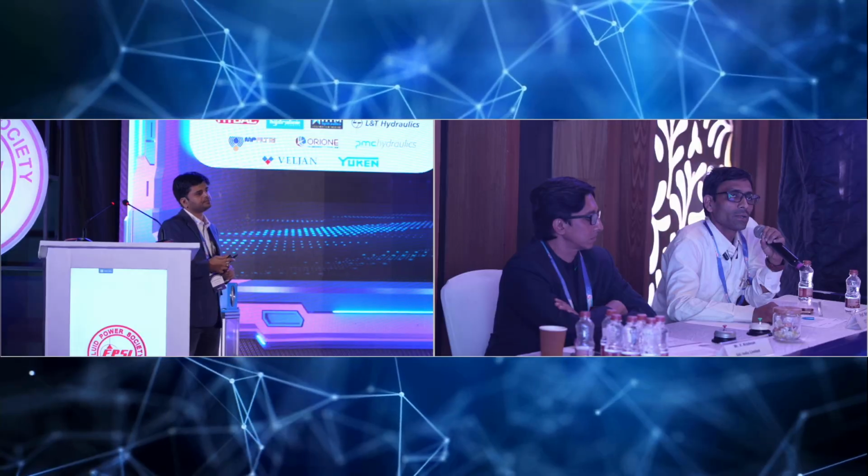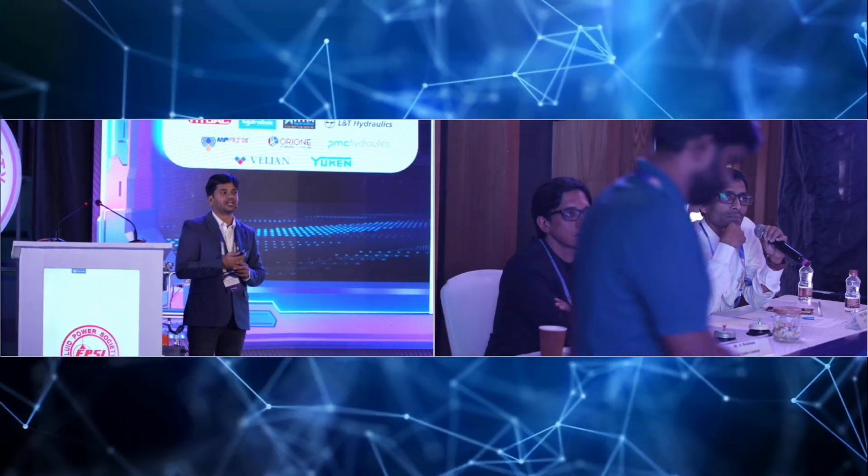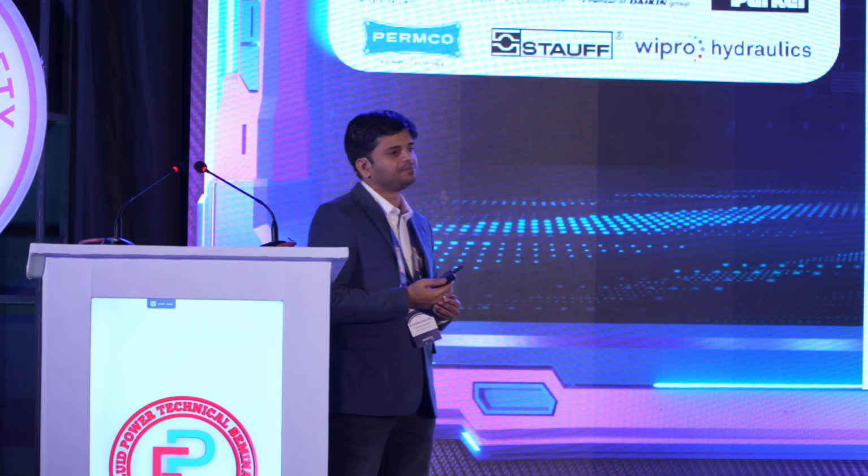Okay, and the second one was that you are measuring this pressure pulsation experimentally. Yes. So obviously, as the amplitude of pulsation is, I think, in the range of 5 to 10 bar, what kind of pressure sensor have you used for measuring this amplitude? We have used something called a Kistler sensor, a Kistler fast sensor. Very expensive one. It's like a tablet. You can swallow it. It's very small, but very expensive. Yeah, that's exactly what we have used. It's a pressure transducer. Okay.